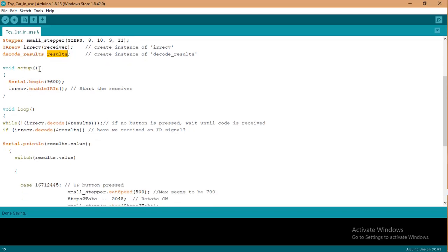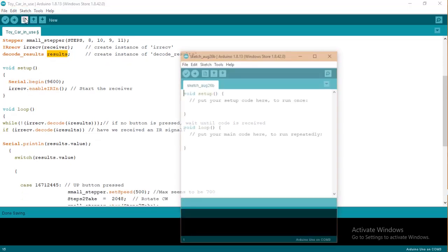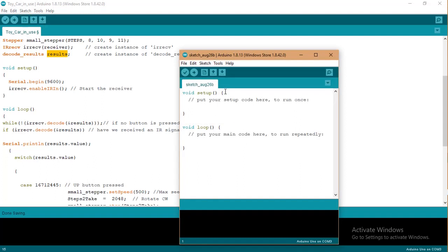Now, whenever you create a new Arduino program, it comes with this too. You have the void setup and the void loop. As they've said here, in the void setup you place everything that runs once. For example, something that happens when the program is loading, things that don't change and only run once in the code.